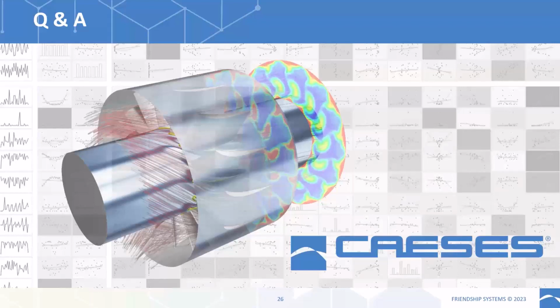So I guess this is related to what we've shown here for thickness distributions. In the approach that you showed, you used thickness distributions on hub and shroud and the blending that did not include the leading edge and trailing edge, but they were added separately as edge definitions. And I guess the question here is whether you can have a thickness distribution which includes the leading and trailing edge as well.